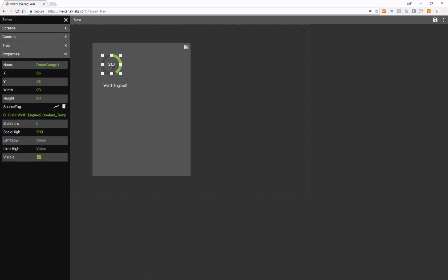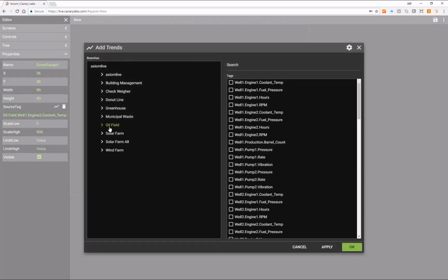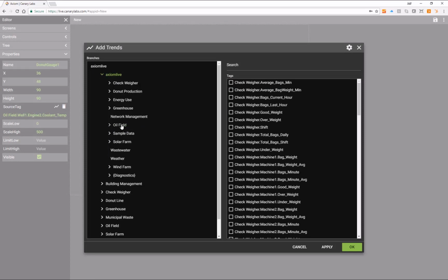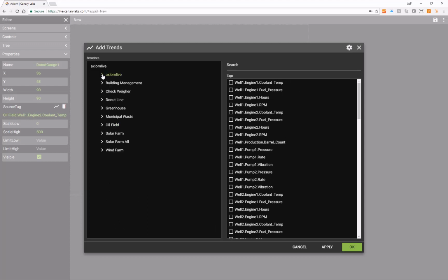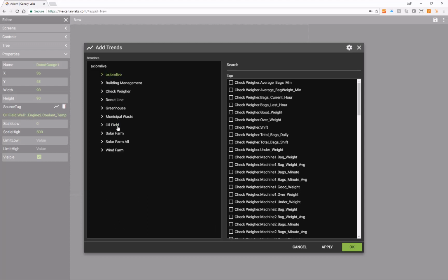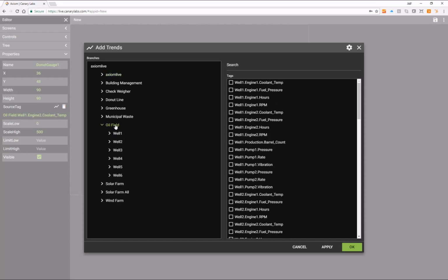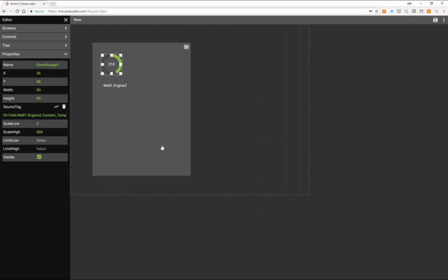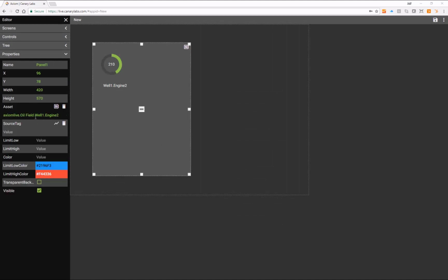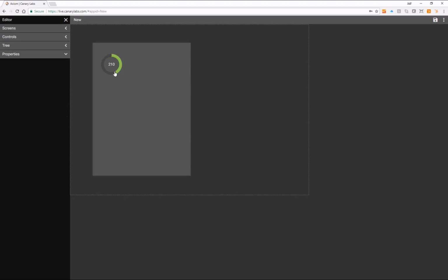It's important to note that when using asset model, you must select tags through the asset model itself. If you navigate to the data sets that contain the asset model instead, the asset will not properly update. So instead of using the view for the historian, I use my asset model view to select all tags. To remove the asset model from the panel, use the trash can, and then choose which controls to delete.